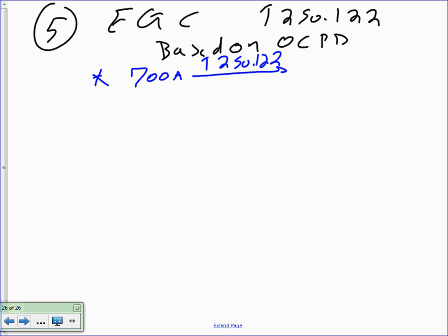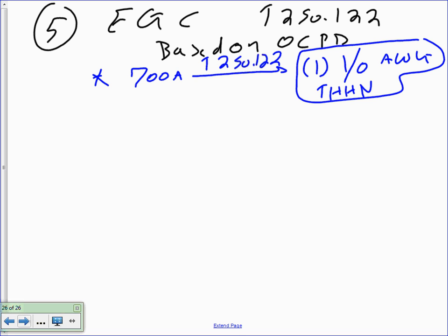We're engineers, so we're vested in the copper companies; we don't pay for the cables. So what size and how many conductors? 1 conductor, 1 AWG, most likely THHN, covered or insulated. Could have covered ones, green covered conductors.